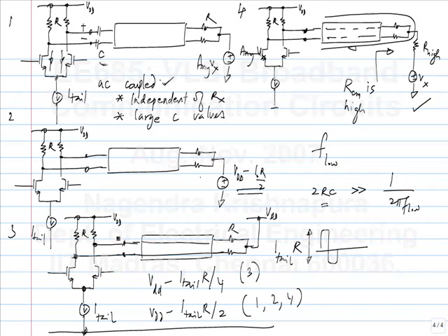Yeah, simply because it won't saturate the transistors, right? If you have the common mode voltage high, it will not saturate the transistors. So either you can accommodate a larger swing or do something of that sort. Is this clear or no? There is a lower limit on the output common mode voltage of the transmitter, because you don't want the transistors to go into triode region. The topology that gives you the highest possible output common mode voltage is the one that you want to choose from this point of view.